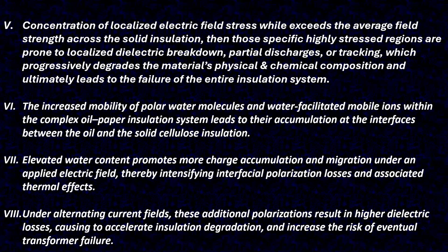The increased mobility of polar water molecules and water-facilitated mobile ions within the complex oil paper insulation system leads to their accumulation at the interfaces between the oil and the solid cellulose insulation.